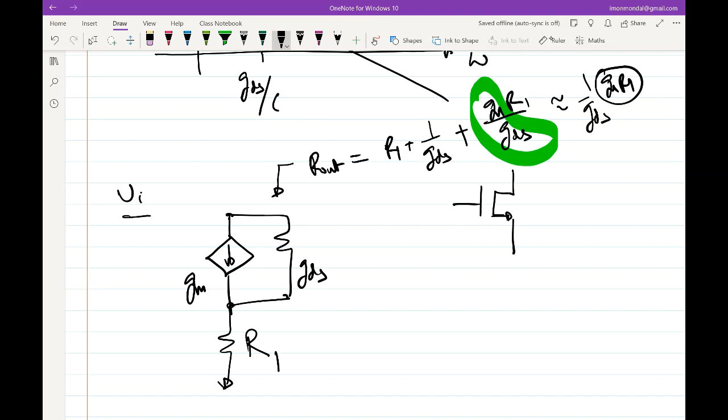Now, if that makes sense, it essentially means that we have a handle for increasing the output resistance, but the issue here is, what is the effective GM? Or how do you figure out the effective GM? You essentially short the output and figure out the short circuit current, right? The short circuit current by input voltage is the transconductance, right? So in this case, if I short the output and figure out ISC, what is ISC over VI?